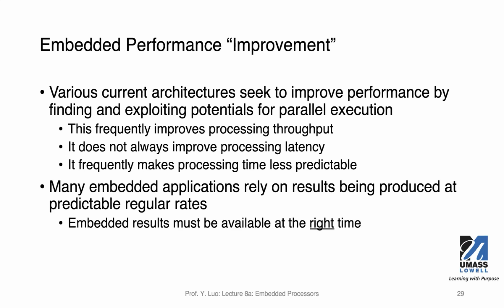There are hard real-time systems and soft real-time systems. Hard real-time systems are where you have to follow exactly the schedule. You have to get your input signal within the first 250 milliseconds, process it in the next 500 milliseconds, and then apply control on the actuators in the next 100 milliseconds. And the next round goes the same. That's a good example of hard real time. So everything has to be timed precisely, and your system will go on like that.